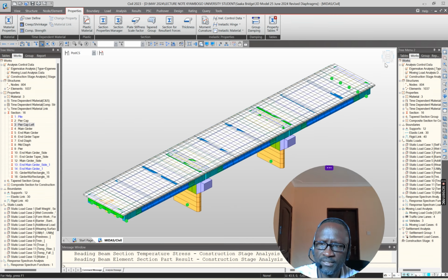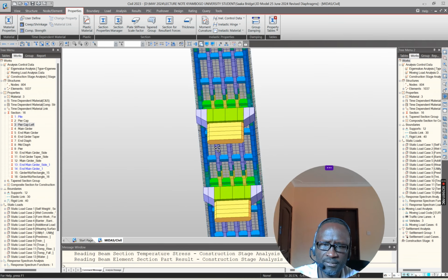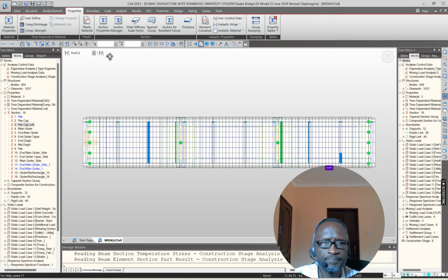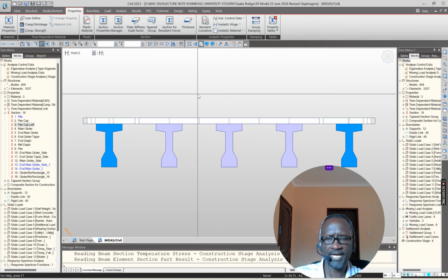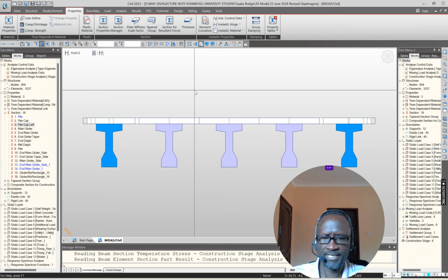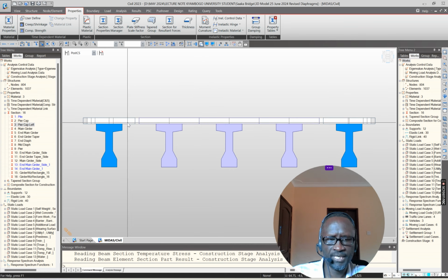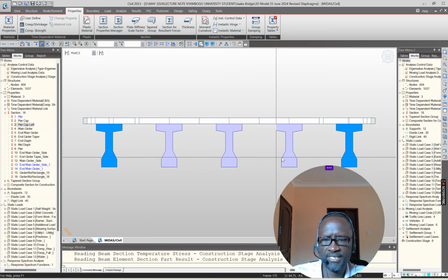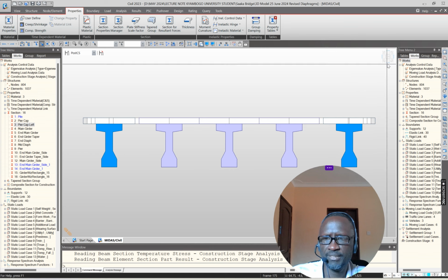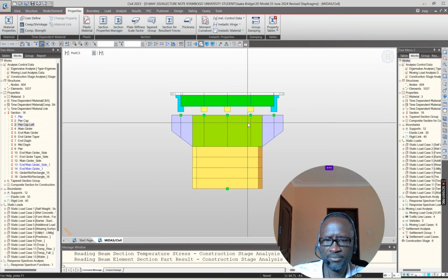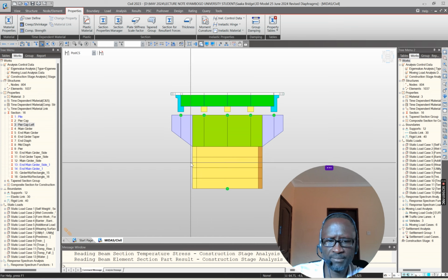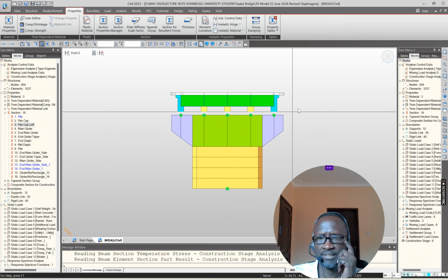It comprises five precast I girders and a slab of 225. These girders are all here. This is the girders' mid span, and then it has two pier supports with tapering pier cap. This is a pier cap of about 6.9 meters or close to 7.